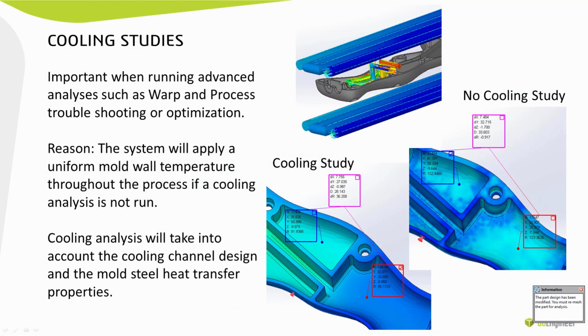So we'll look at cooling studies. With SolidWorks Plastics Professional, you don't have the option to run cooling studies, but I feel it's really important to run a cooling study when you're running an analysis, especially when you're looking at warpage, because non-uniform cooling is one of the reasons why you'll get part warpage. Also, if you're trying to do process troubleshooting or optimization on the injection molding process using the simulation software, it's good to have the cooling lines modeled true to what they are in the tooling, and you can enter your values and everything for the water lines.